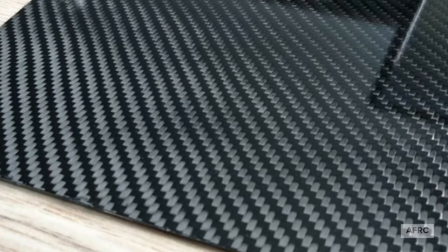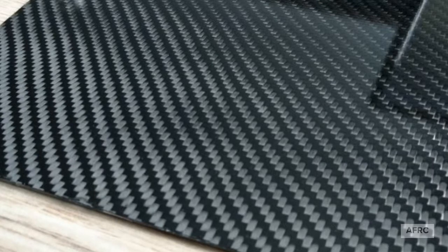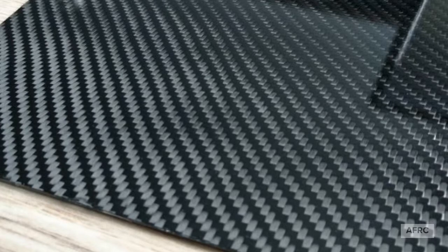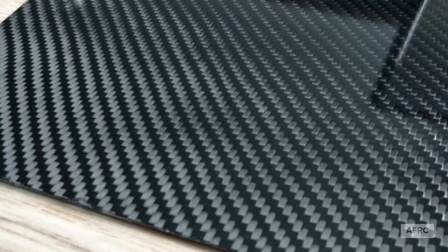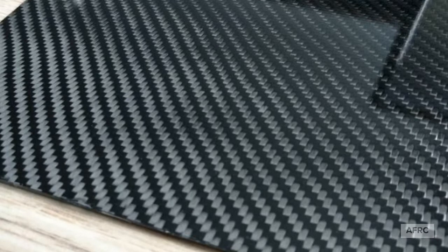One of those things is that when they're mixing the epoxy, it comes in a two-part kit and there are mix instructions, and typically they're very specific. It has to be weighed out because it has to be mixed by either weight or sometimes volume. If I didn't witness that, I can't really give any assurances as the inspector that it was done correctly, and that could compromise the strength of this structure.